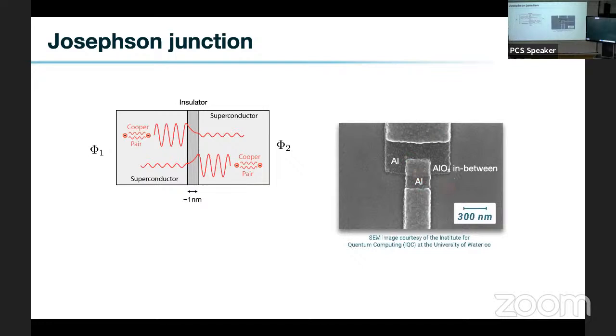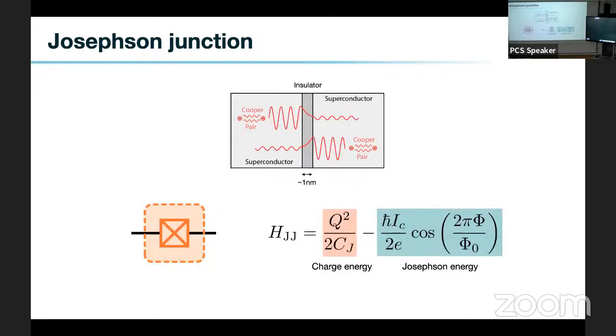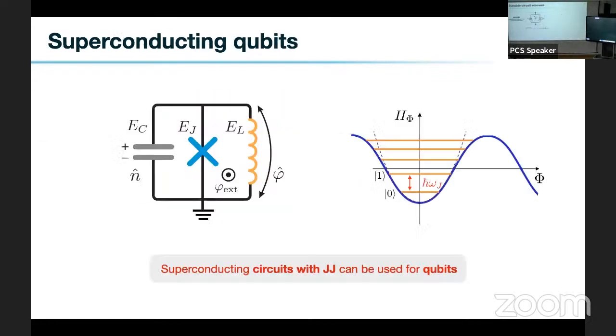So it has everything in it in a sense, right? That's true, but to make a superconducting qubit, we need a relatively large capacitor. So that junction itself is not enough to make a qubit. So in general, we put capacitive pads and we connect these two pads using the junction. This is the basic structure of the superconducting qubit.